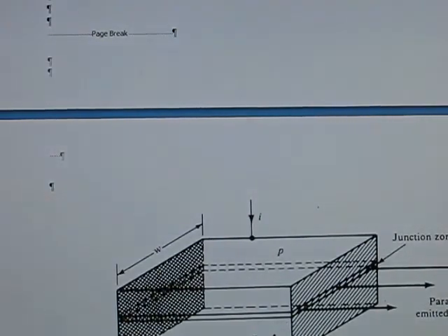So when this is in fact in the laser mode, we get relatively high power output, and notice that this is not a spot. It comes out parallel. So diodes, if we could look at this, we would see kind of like an oval pattern, and then that has to go into a micro lens which focuses this, and since laser diodes are typically used with single mode cable whose core is quite small compared to multi-mode, it has to be focused very precisely so that it can pick up the core itself without any losses in the cladding and things like that.